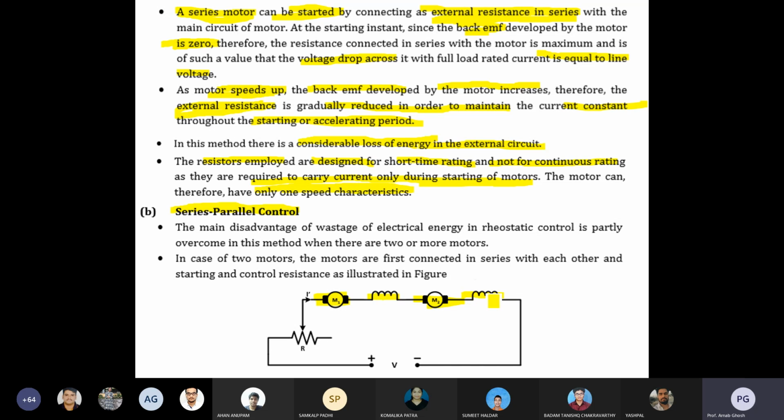Okay, so you are connecting them in series. Parallel means more current if the loads are huge. The current drawn by the motor will be more, so you can configure the motors in parallel. In the case of high voltage applications, you can subdivide the voltage by combining both motors in series, and you can control the voltage throughout the motor terminals.